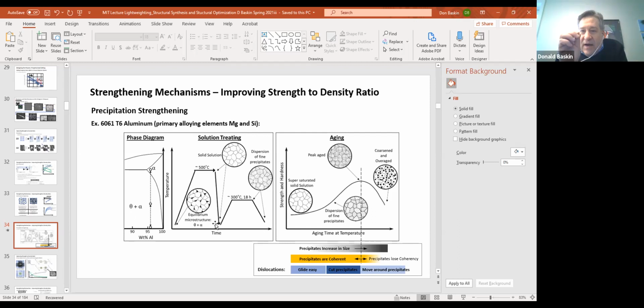First, very, very fine. They go a little bigger, a little bigger, a little bigger, and then at some point they got so big that the material wasn't very effectively strengthened. Your raisins turned into dates, and it wasn't very strong. There's a point there where the precipitates hit an optimal size, the size where they provide the most strengthening.